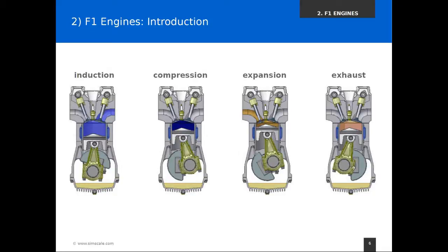So once we've reached the point here, we will do another revolution. Actually, this should also be mentioned here. So it goes down, it expands. This is called the expansion stroke. And then what do we have then? Once the piston has moved all the way down, the gas is still there, but now it's burnt. It's burnt fuel together with, well, whatever's remaining of the air. So it's probably mostly nitrogen and less oxygen than before, or almost no oxygen.